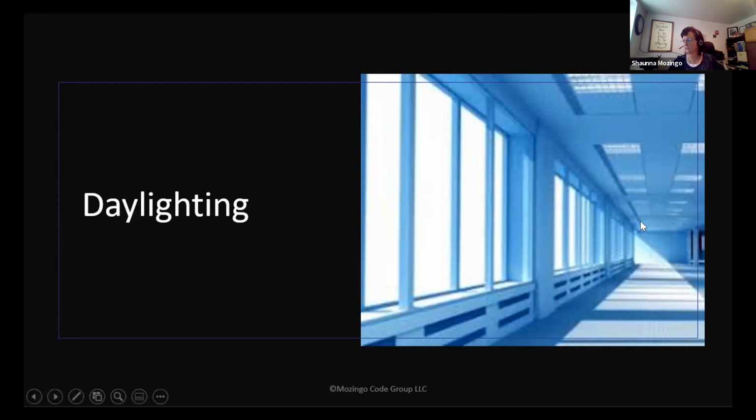If I have a room like this that you see, and I have daylight coming in, maybe I have a requirement for some daylight responsive controls, but I also have a requirement for some occupancy sensors. So I have an occupancy sensor over here saying, hey, I don't have any more occupants in the room, and in 20 minutes my lights are going to shut off because there are no more occupants.